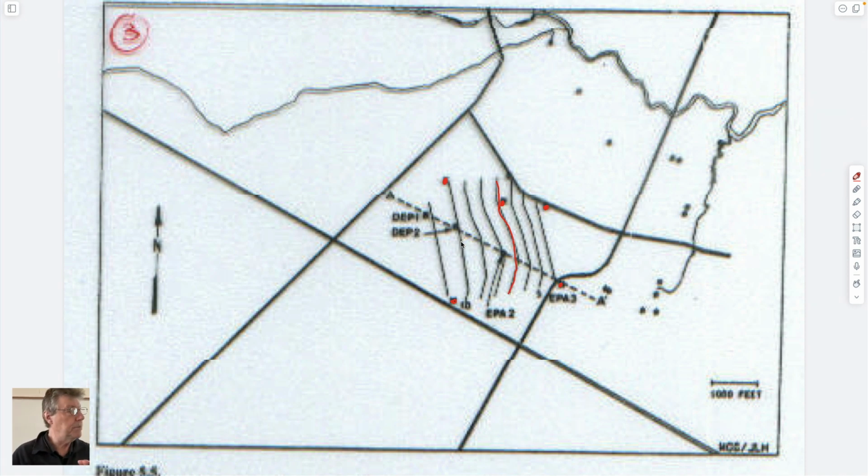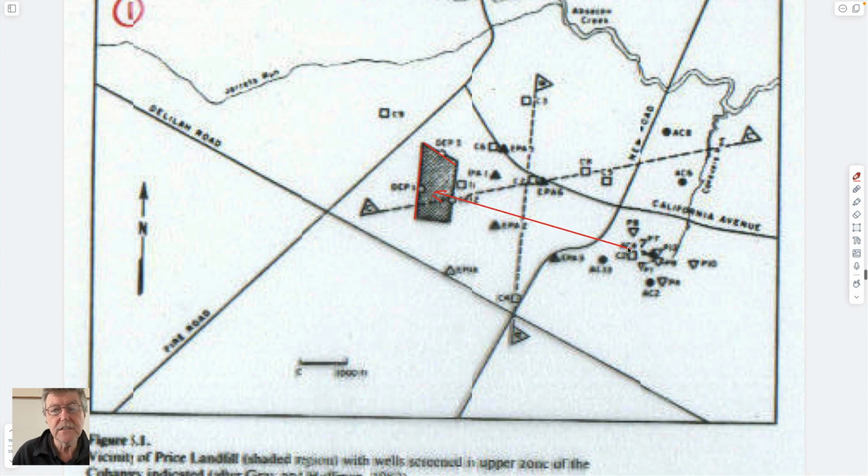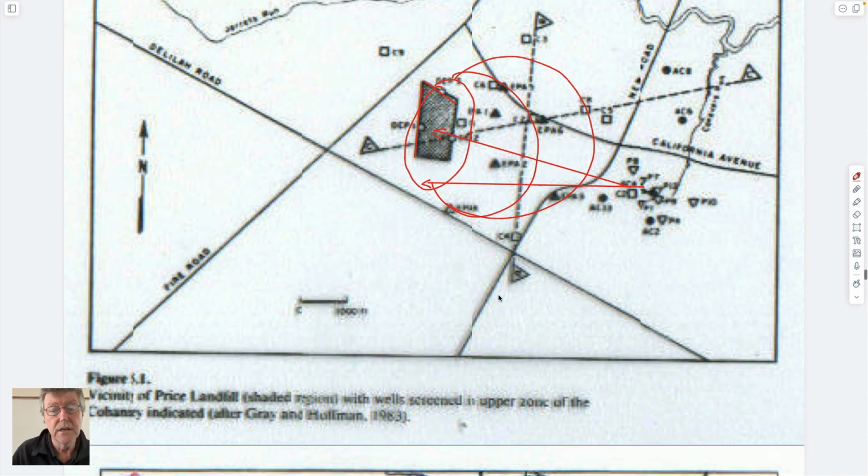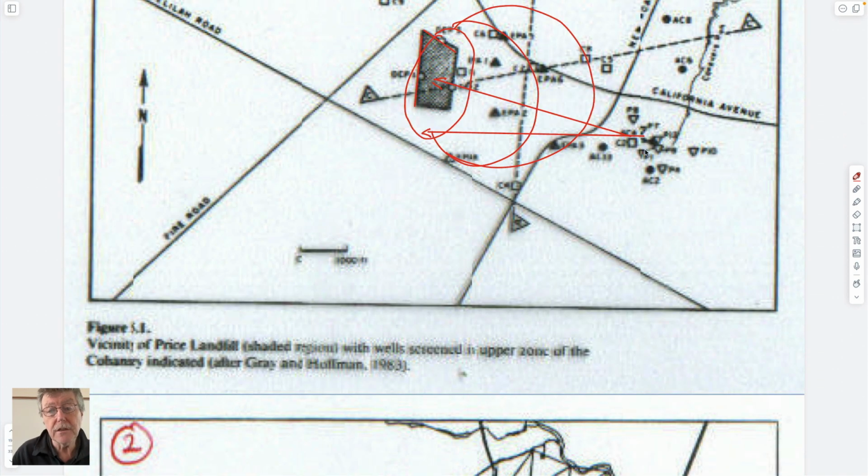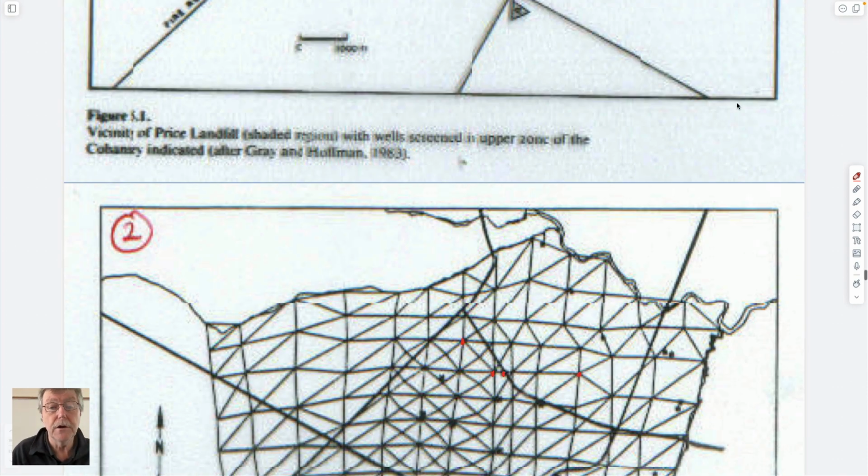This would be upstream, so this would be progressively higher, and this would be progressively lower. You know that flow is going to be perpendicular to these largely, and so you'd be able to look up from here. Actually, it doesn't work out quite that well here, because if you looked perpendicular to the wells here, you'd look in this direction, and it seems that if it's detected here, well, it is kind of that direction, but not quite, right? Slightly off. So maybe it's diffusing sideways and then coming down as a plume as you go downstream. So that's why it's occurring in that behavior. And then the plume is clipping these things, but maybe the maximum concentration would be going down somewhere else, and maybe someone else's problem as well.